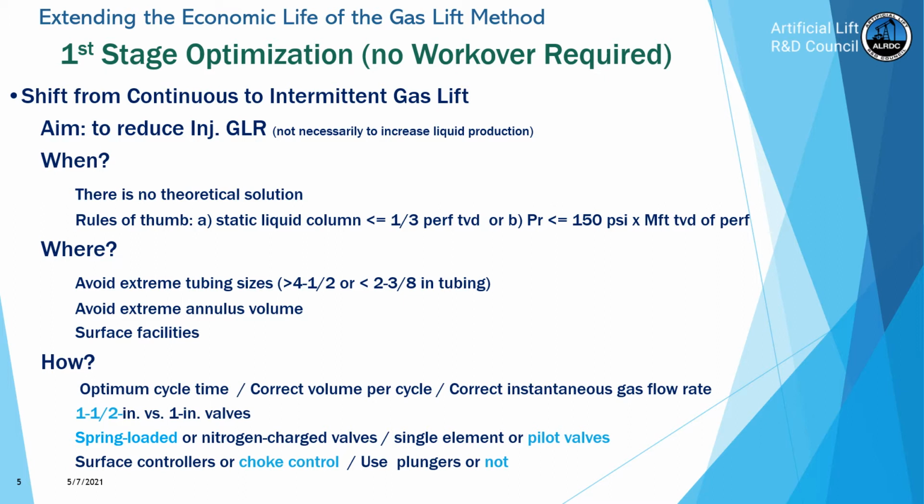So, for example, if we have 5% liquid slug loss in a well that is 10,000 feet deep, where the operating valve is at 10,000 feet deep, then we're going to lose 50% of the initial liquid slug that will never be produced because of fallback losses.